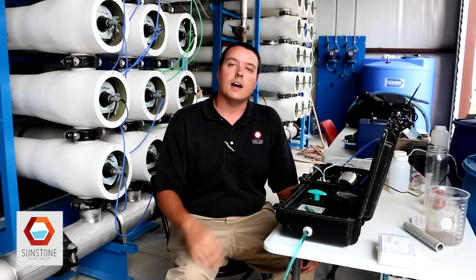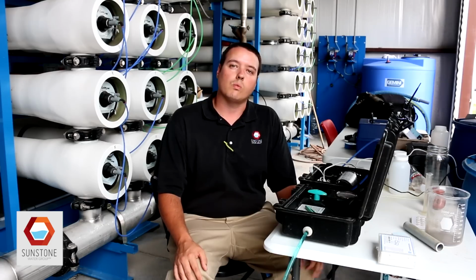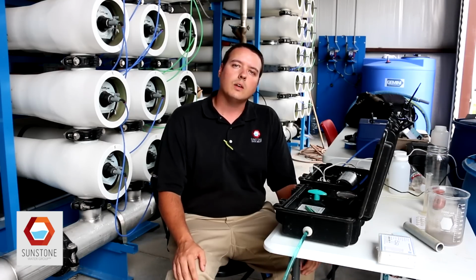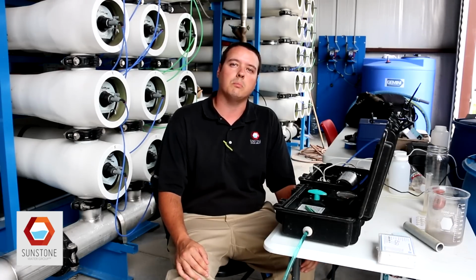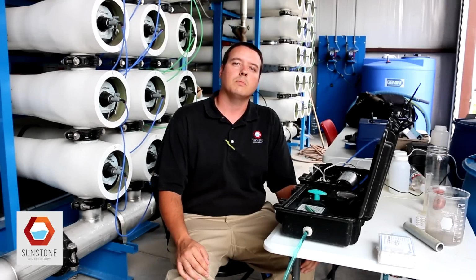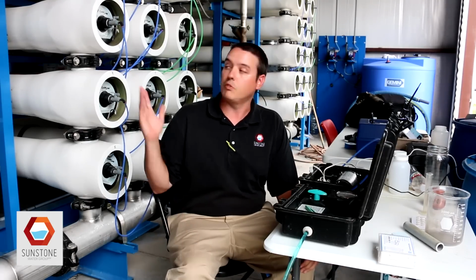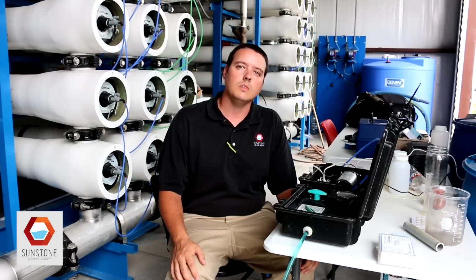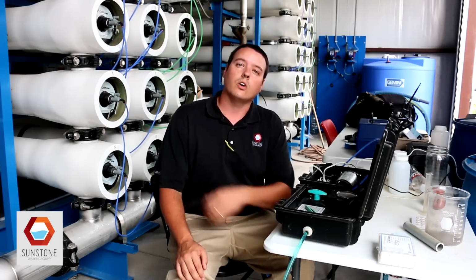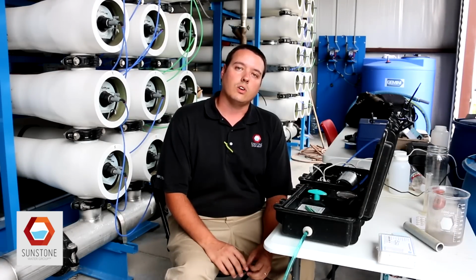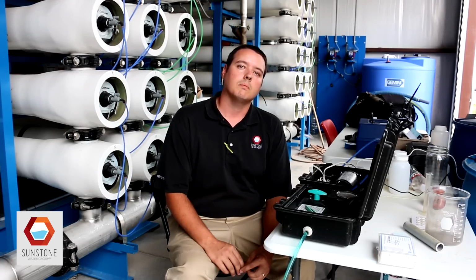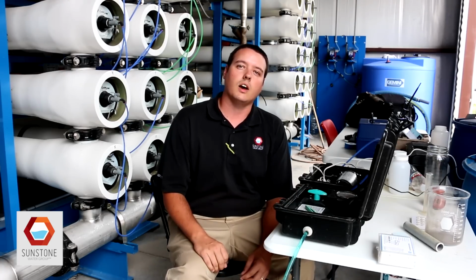And so what we'll do right now is we'll run an analysis of the raw, untreated water, and then we'll compare it to different stages of pretreatment. And this will give us an indication of how effective each stage of pretreatment is in cleaning the water before it enters an RO system. The cleaner the water, the longer an RO system can run in between chemical cleanings, and also the lower the energy cost will be to run the system. So here's the SDI on raw water.